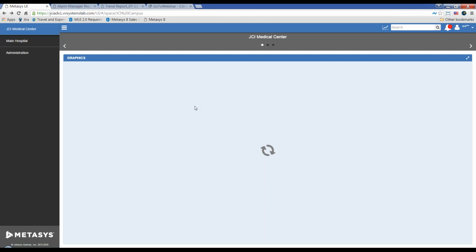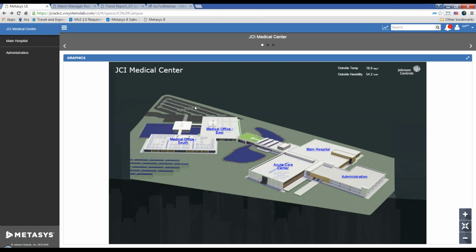So to kind of recap everything, we're pulling in information that may have been in disparate places depending on the building automation system. For instance, if that data is in a user view or in the all items tree, if you're familiar with Metasys, or in a graphic, we're pulling those all into this equipment and space-based framework, which makes it really easy to find the data, makes it easy to diagnose problems for the entire mechanical system, and easy to command and make adjustments to fix those issues.